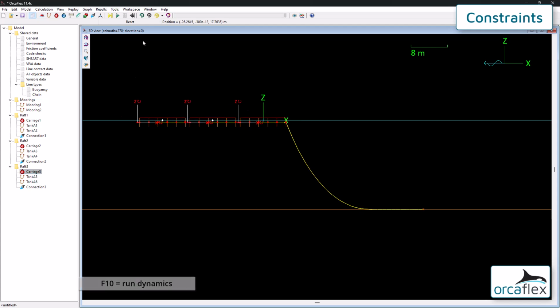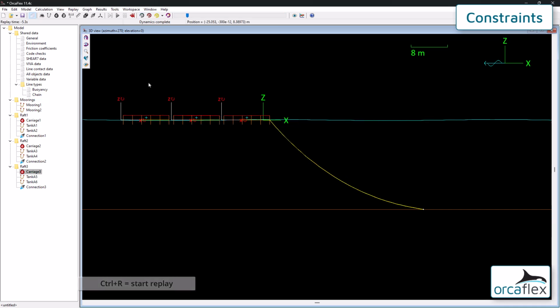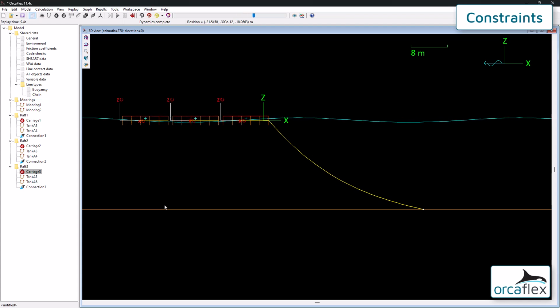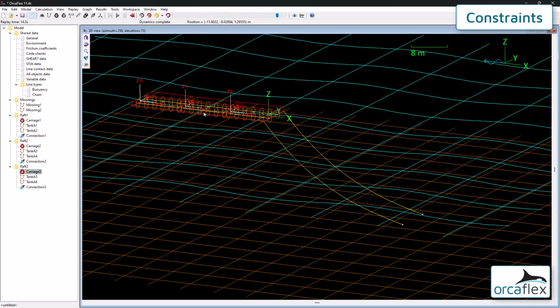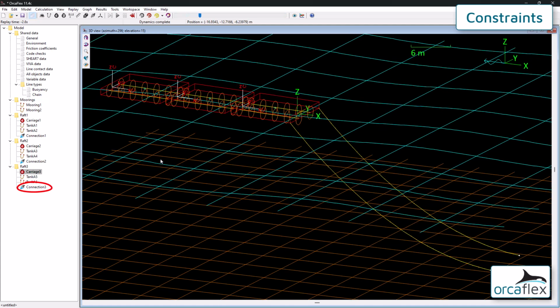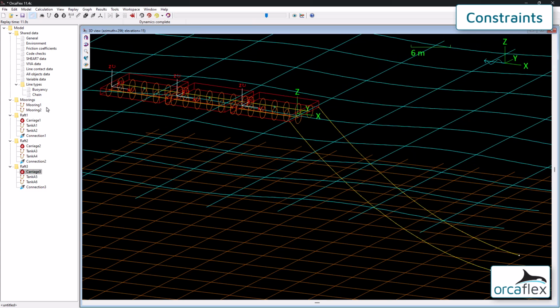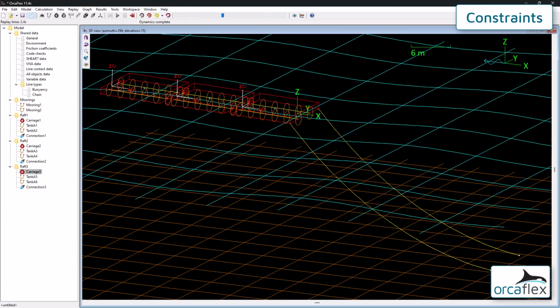Dynamics can be run now, but at this stage, the 3 rafts are acting as one rigid body. The final step is to enable the appropriate rotational degree of freedom on each constraint, in this case RY. Connection 3 doesn't yet have any child objects connected to it, so it doesn't need to be changed. If there were to be further rafts, we could leave this constraint here, otherwise it could be deleted.